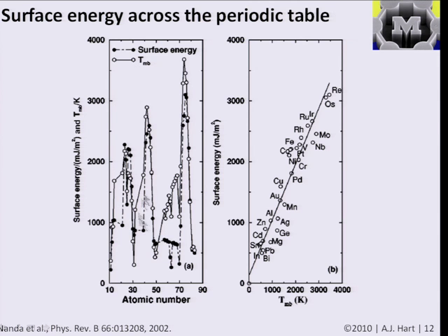The smaller fluctuations here and what causes them are beyond our scope, but generally there's a correlation between the stability of a solid and its melting temperature. And that analogy can also be applied to small structures, because if you have a lot of surface and surface is less stable, then that can affect the melting temperature of a small solid. And how stable or unstable that surface is for a particle of a particular size, and what the particular bonding characteristics of the material inside the solid are, affect the specific melting point of a nanoparticle of a certain material and a certain size.